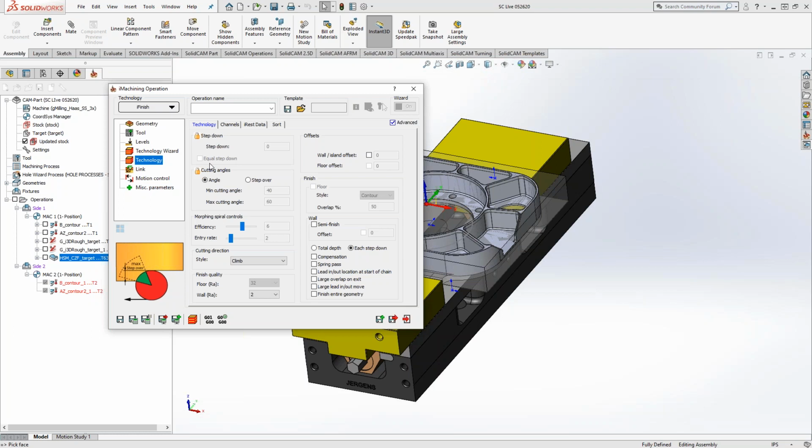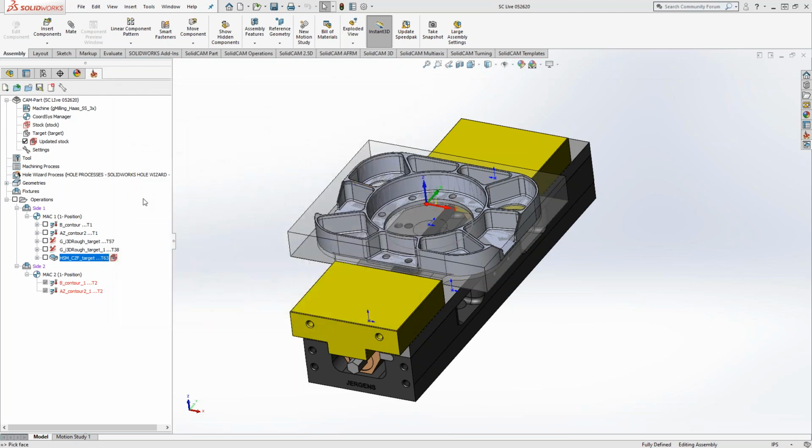Okay, so Scott's question. If you use the bull end mill in multi-tool 3D iMachining, would it have done the floors and the corner radius? Basically, it considers it as the same tool. It would just do the corners, recognizing that it's not going to gouge it. But yeah, it would do the corner radius just because of the shape of the tool. Any geometry that is there, it would recognize it.